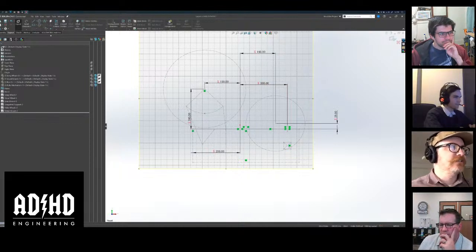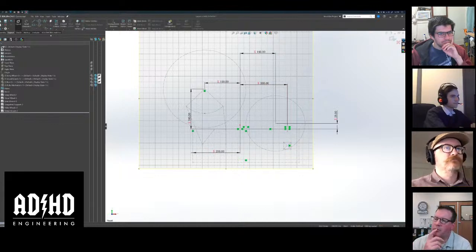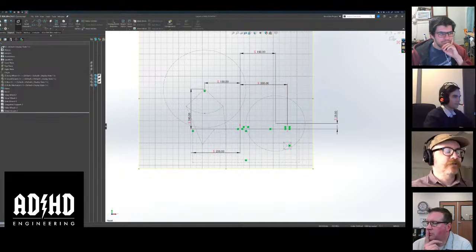Ideally, and I haven't figured this out yet with SolidWorks Connected, you would have a library of blocks, and those blocks would be the geometry for commonly used items of whatever kind. Then you would build a layout sketch with those blocks in the correct orientation, and then build your assembly from there. Right. Okay.